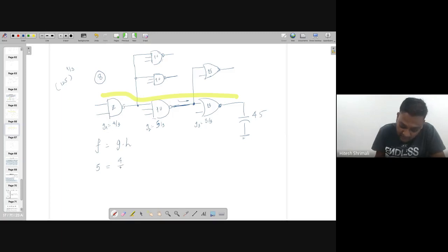It's going to be equal to 4 by 3 multiplied by c out, which at this point, having 3 NAND gates in parallel, is going to make 30 divided by z. So if I take z one side, I'm going to have 4 multiplied by 30 divided by 5 multiplied by 5. So this makes 8. So you can see that even with the back calculation, it matches the number that has been given to you.